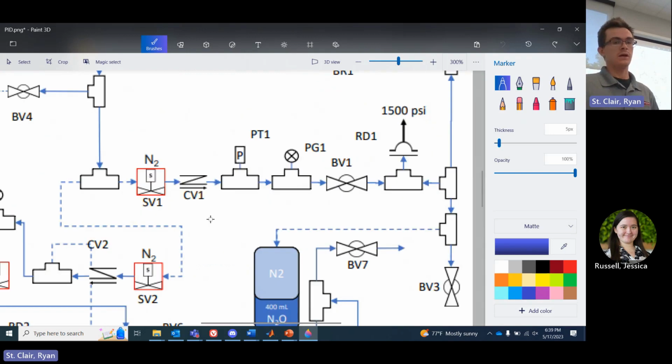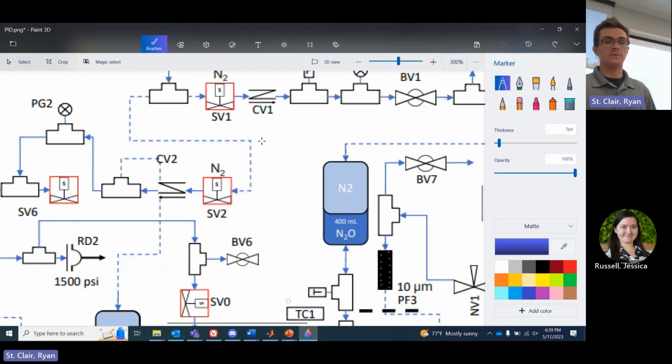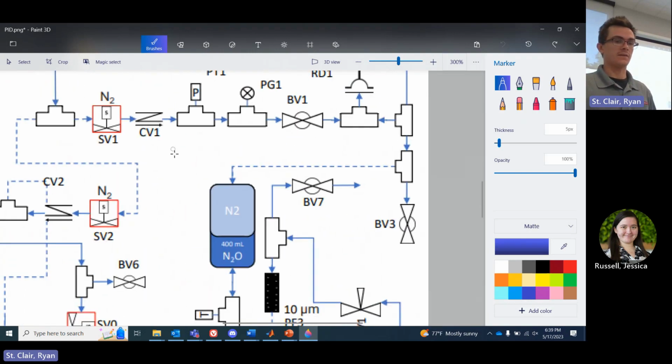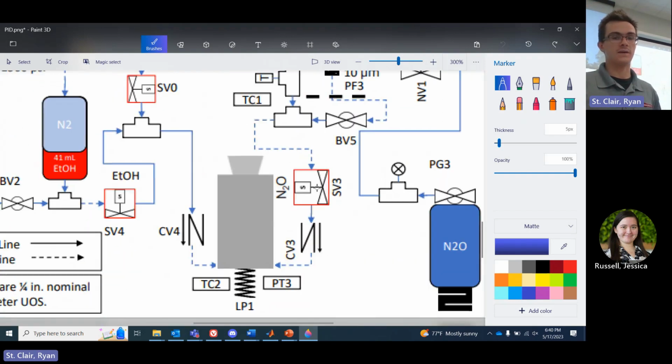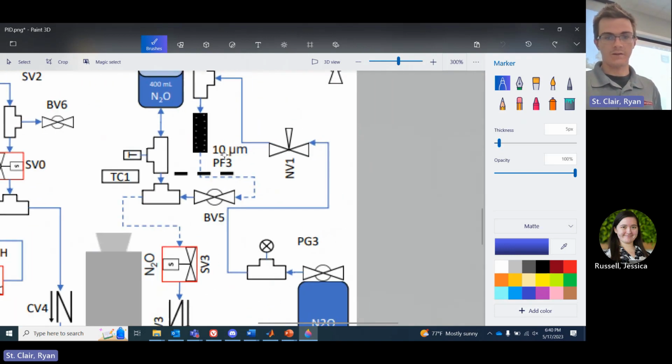like say for example, if you were to control your flow, you didn't have this valve right here, but you're only using this solenoid valve 1 here, then there's a lot of compliance in the system, and so you might tell it to turn off, but the pressure is actually going to go kind of like that. It's not going to immediately shut off, and you get closer to that effect when you have a valve closer to your rocket engine. And then it goes across the injector, or the check valve into the injector, and there you have that. So there's a lot of things going on here.